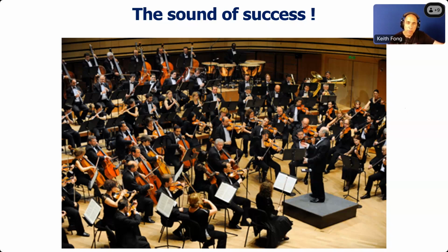That's an excellent question, Kit. For example, let's go to extrusion. One simple extrusion is when they manufacture a hose: outside diameter, inside diameter, and thickness, right? Obviously, those 3 measurements are dependent. T-squared is going to be very useful to control the process and declare it out of control whenever it really is. If you have an SPC chart for the outside diameter, inside diameter, and thickness, it's just information, but it's not going to give you the right decision when declaring the process out of control. But we have other cases in molding, for example, with more than 3 measurements.